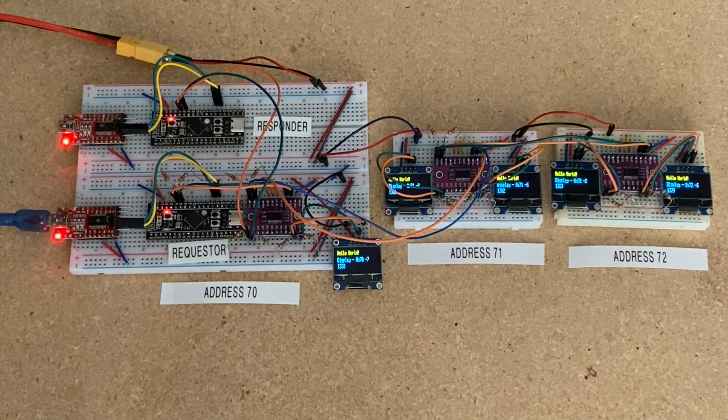I put this prototype together with more than one multiplexer, which would handle multiple addresses of the same kind. So on the first one, you could handle another 7, and on the second one you can handle another 7, and on the third one you can handle 8. The reason it's 7 on the first 2 is because you've got to go from that multiplexer to the next multiplexer, which takes one of the 2-wire pairs.